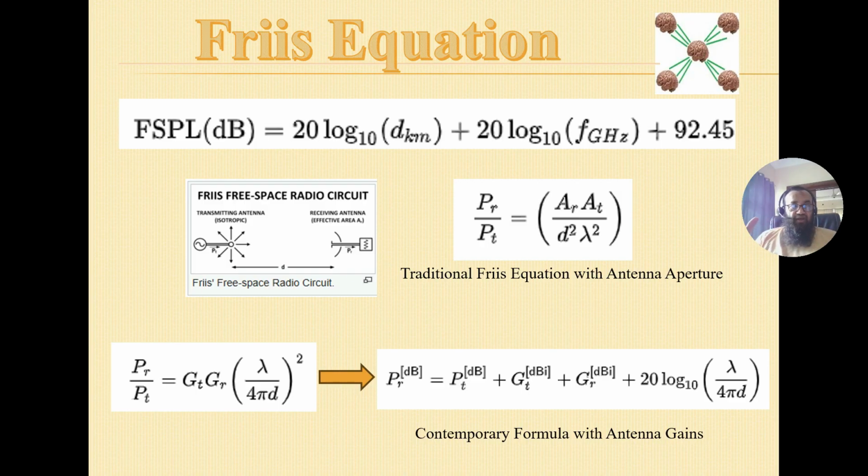Basically, from the IDU, we send some kind of power to the ODU, because the ODU is an active equipment. ODU has some active components. ODU also has a gain. Whenever it is receiving a frequency, it's pre-amplifying it, and it is doing some frequency conversions as well. It is doing three, four things. So that's why it needs some power, but that power is not fed to the antenna. Antenna doesn't use any power. Antenna is a fully passive device.